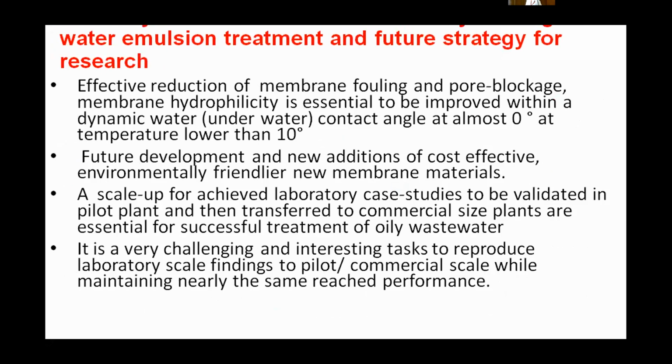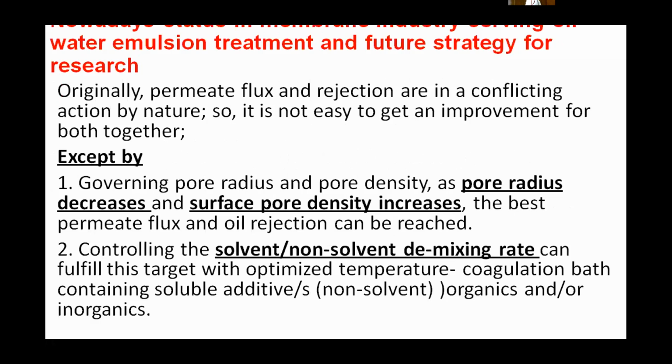Finally, this means that the membrane application for water-oil emulsion separation is a promising technique and has future trends to be applied. But it depends mainly on the hydrophilicity and how to enhance it. Also, as a final conclusion, we need to govern the pore radius. As the pore radius decreases and the surface pore density increases, this will enhance the permeate flux and enhance the oil rejection to be reached.